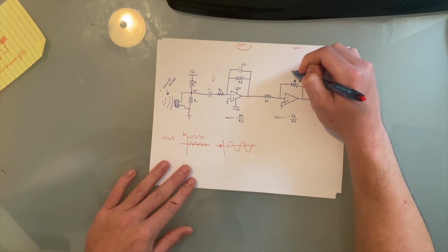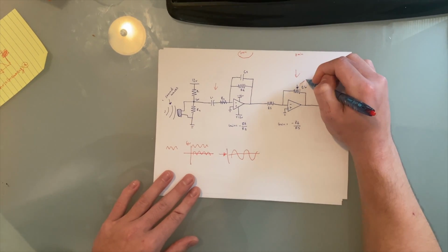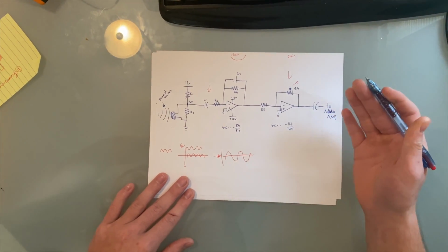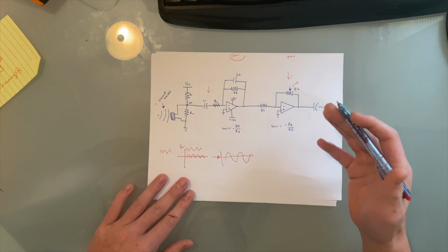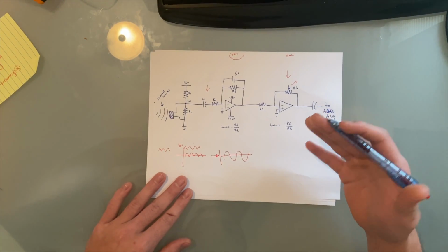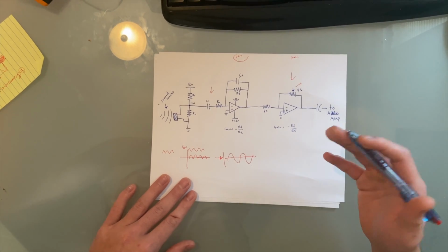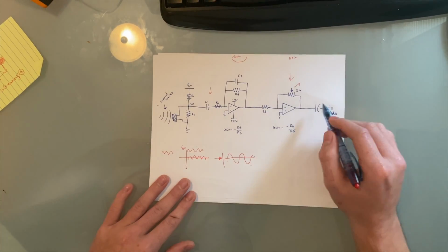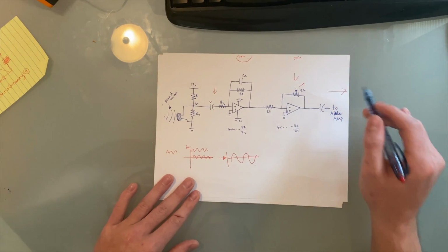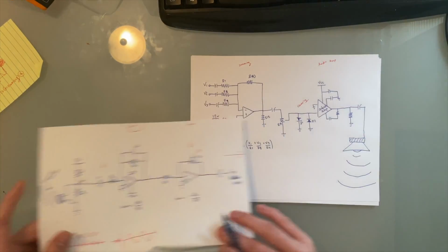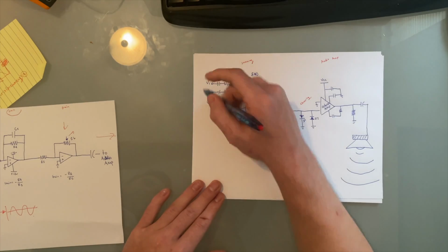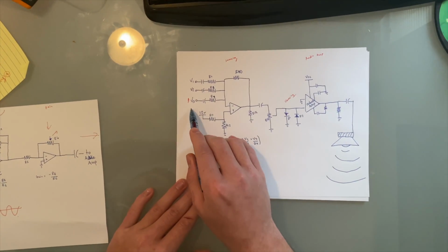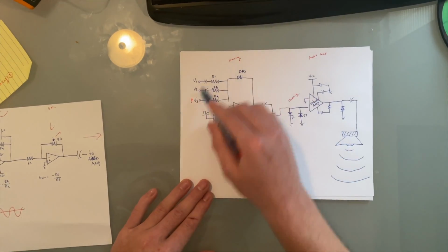And then this is another gain stage, and this is a potentiometer. So I can change the amount of gain that the signal is going to receive, so it can look bigger or have a gain of 1, so no gain. And this portion of the circuit will be fed into the audio amplification portion, which you can see right here. It's fed into one of the V's, and this is a summing amplifier right here.